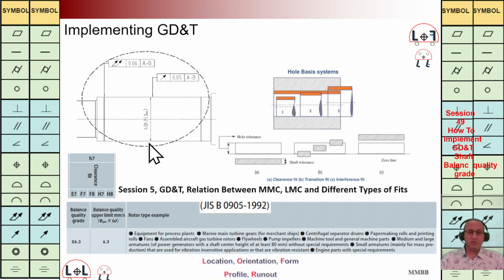Here, in order to qualify our reference axis, we have used these tolerance sizes, this TZ for the size. And for the contact area between shaft and shaft coupling, as we talked about, I guess, in session 5, we are going to have three different fittings. Let's say clearance, where there is no interference between shaft and hole; transition fit, where there is some interference between shaft and hole; and interference fit. In order to assemble the shaft inside the hole based on interference fit, we need to use some tools to hit it or cool it down and then do the assembly.